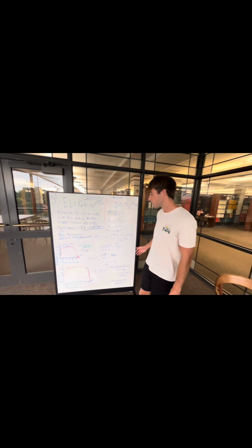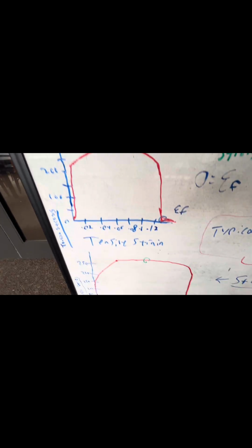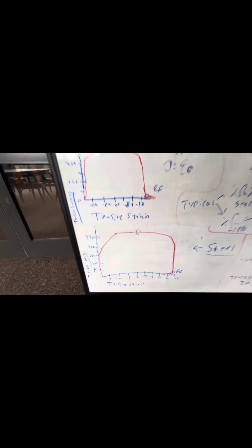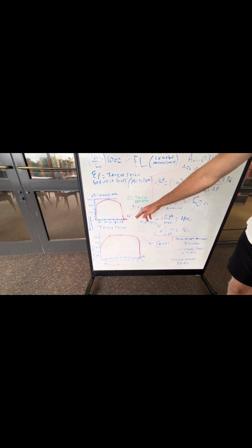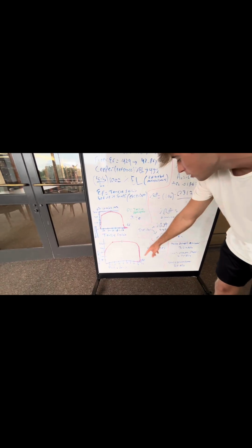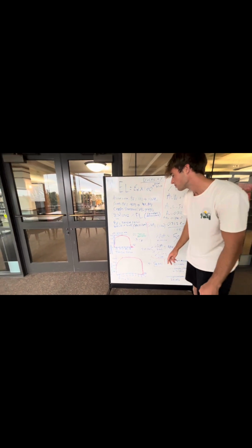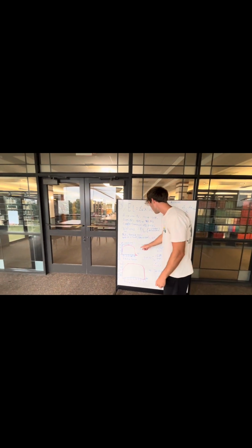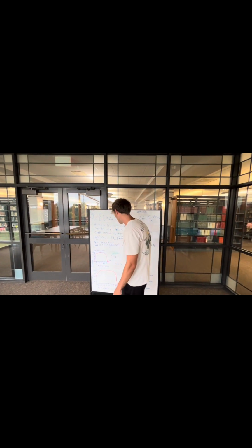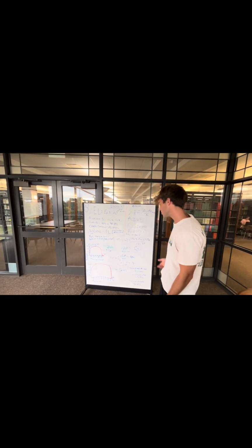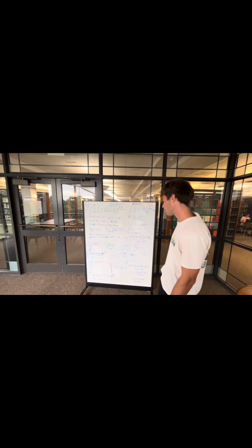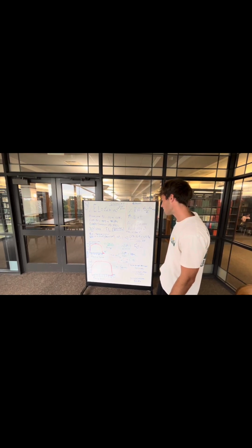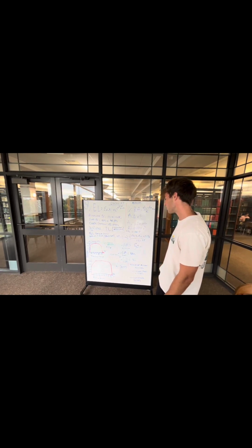And so if we come up here and we look closer to these specific graphs, we are going to figure out that the aluminum graph, that is also a tensile stress versus tensile strain graph, same thing for the steel, which is below. From the graphs, the highest peak is exactly where the tensile strength is. So right here, aluminum would be around 300 plus, because it goes above the 300 line, and for steel, it would be above 250 because it goes above the line.